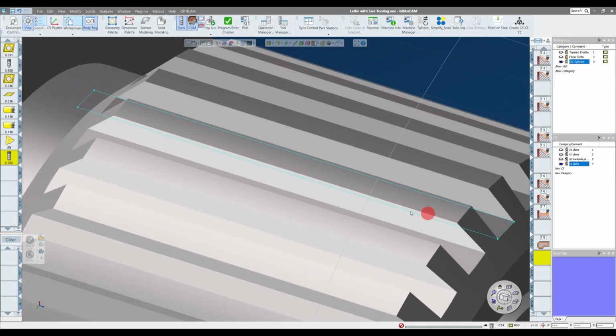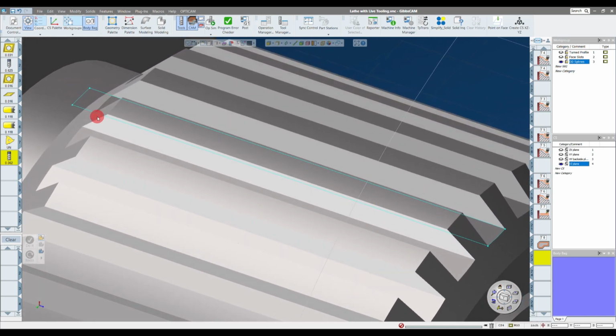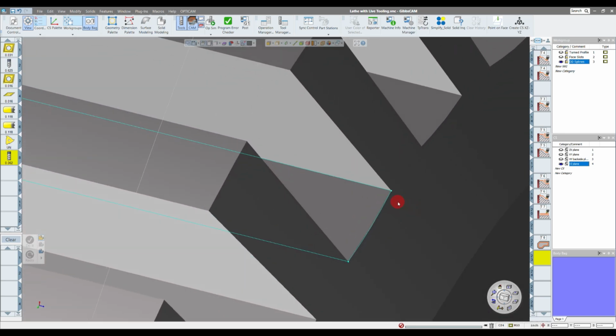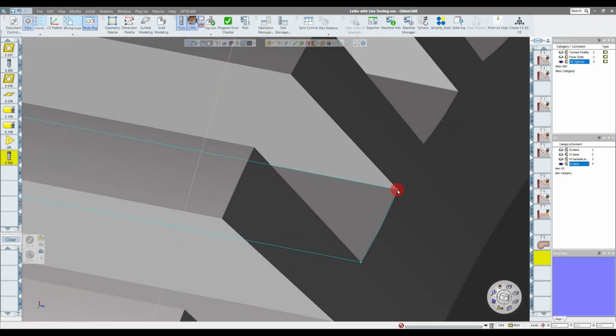Now, because I'm going to do this with a contour, I want to make this an open shape. I just need a U-shaped piece of geometry. So down here at the end, I don't need to parallel a line or anything. I'm just going to select this connector here, which connects this horizontal line to this spline. I'm going to select that connector, hold Control, and select this line.